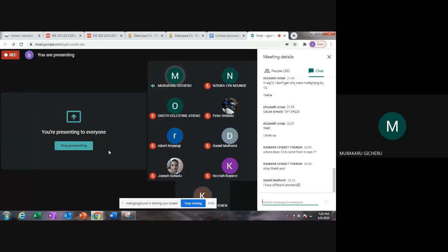But when we're using I average for a class AB amplifier, it's because we're taking the average collector current produced, induced, whatever, by the input signal, which is AC. Yeah, that is making sense.